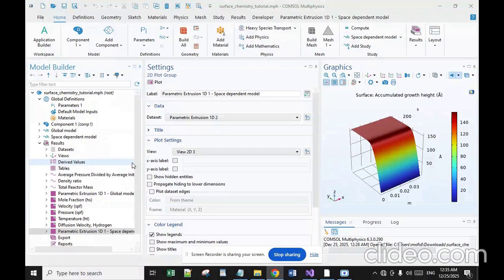Microfabrication processes widely use CVD to deposit materials in various forms, including monocrystalline, polycrystalline, amorphous, and epitaxial. These materials include silicon, dioxide, carbide, nitride, and oxynitride, carbon fiber and nanofibers, nanotubes, diamond and graphene, fluorocarbons, filaments, tungsten, titanium nitride, and various high-k dielectrics.